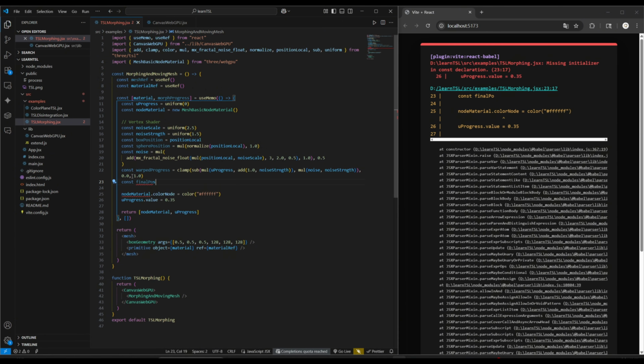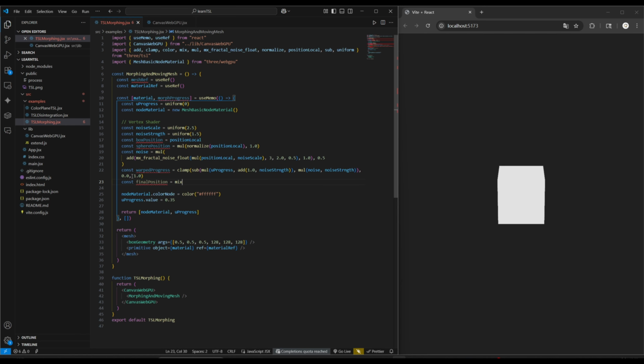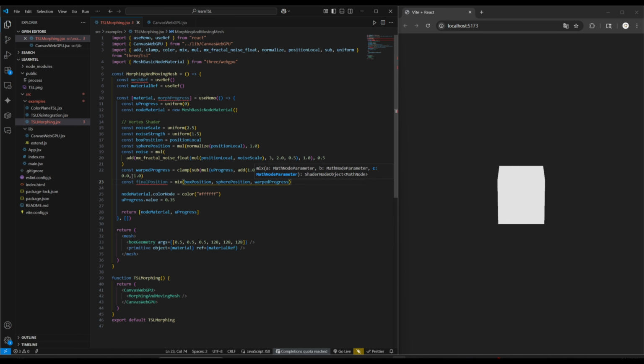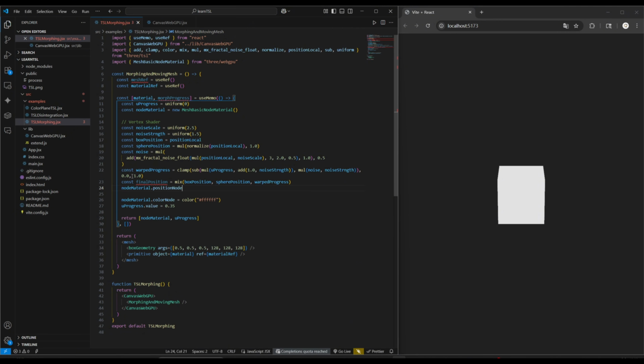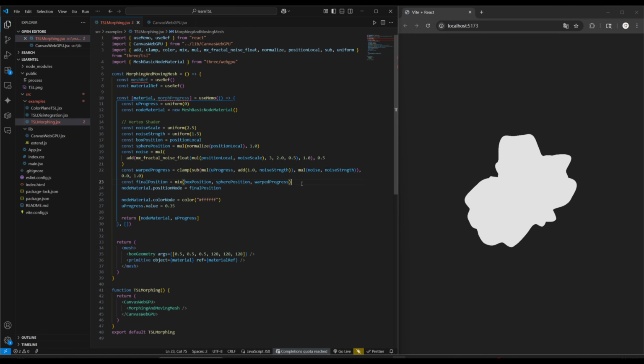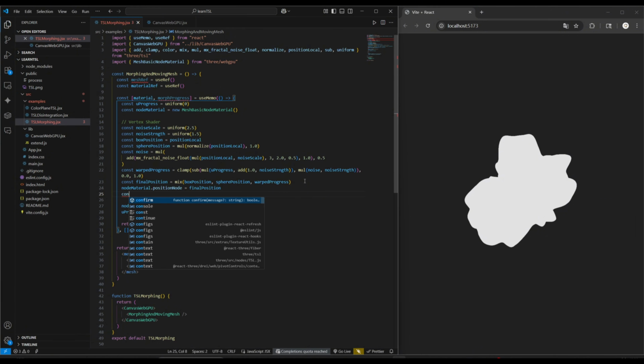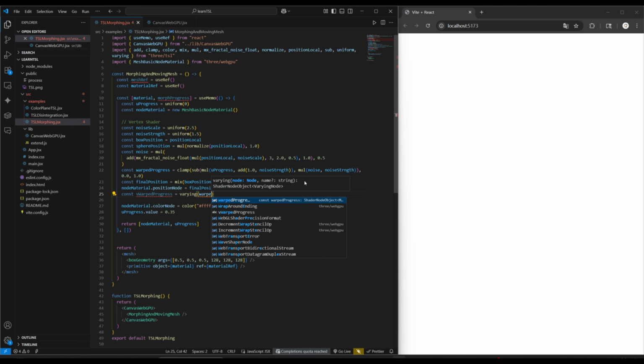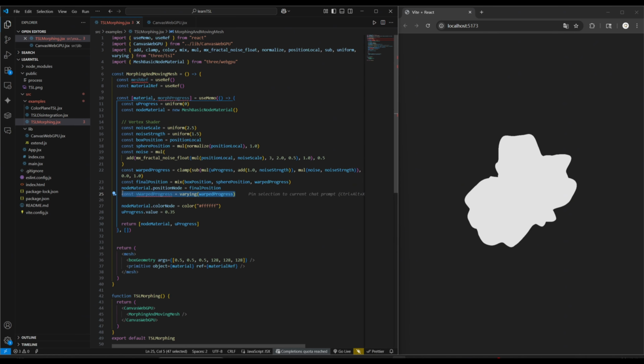We can now mix the cube's original coordinates with the sphere's direction vector. You can think of this as giving each vertex a slider. When the slider is at 0, it's a cube, and when the slider is at 1, it's a sphere. Finally, we'll pass that result to the position node, and now you can see our shape is in an intermediate state between a cube and a sphere. This line of code passes each vertex's local progress to the fragment shader to control the emissive band.